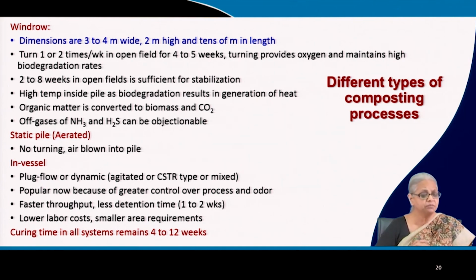Then we come to in-vessel composting. The biggest advantage of in-vessel composting is that the footprint will be very small in comparison to all the other processes, which have a large footprint, land area requirement. In-vessel it can be run in either plug flow mode or CSTR or mixed mode. It depends on how much energy you want to put into the process.